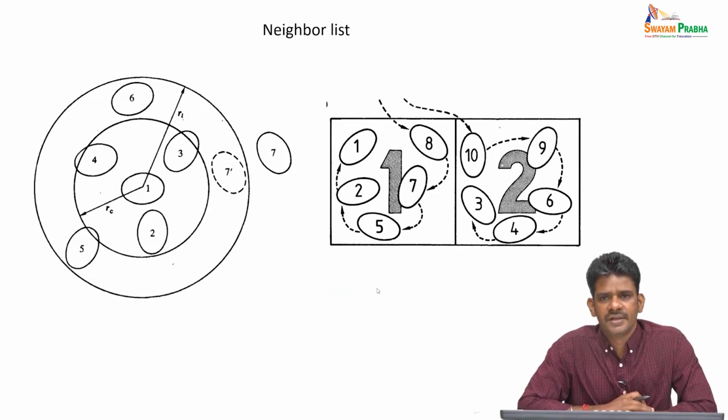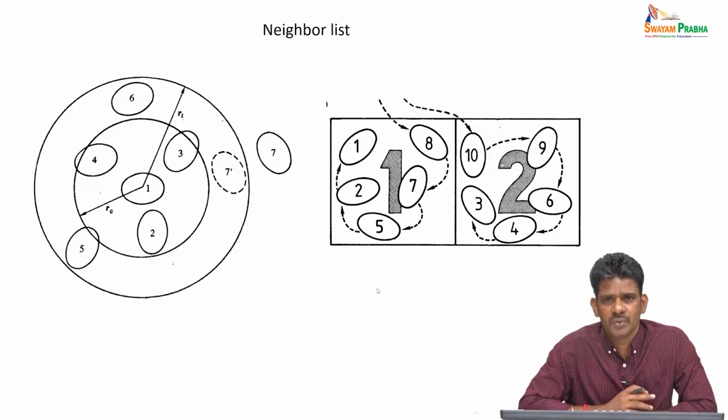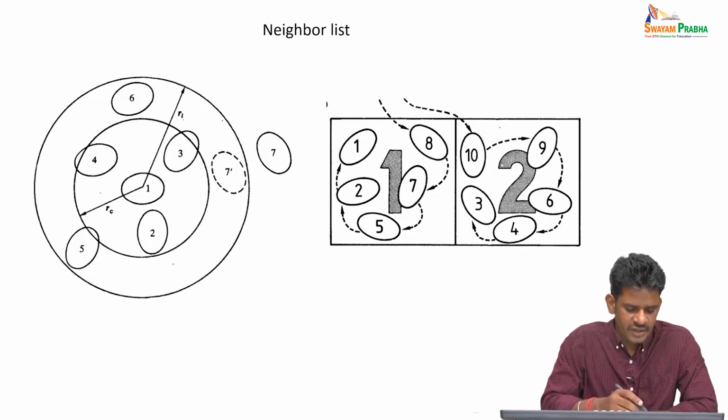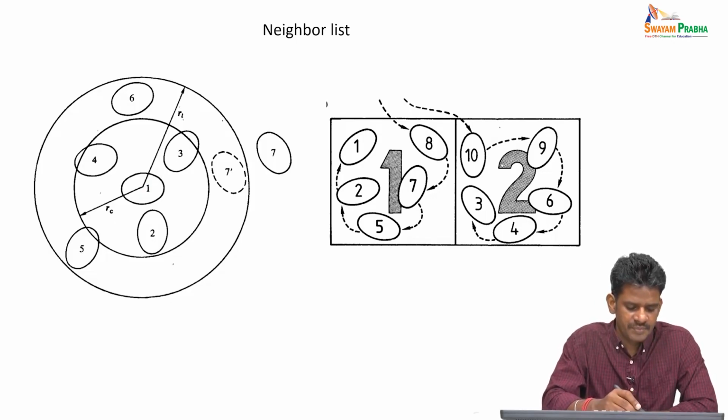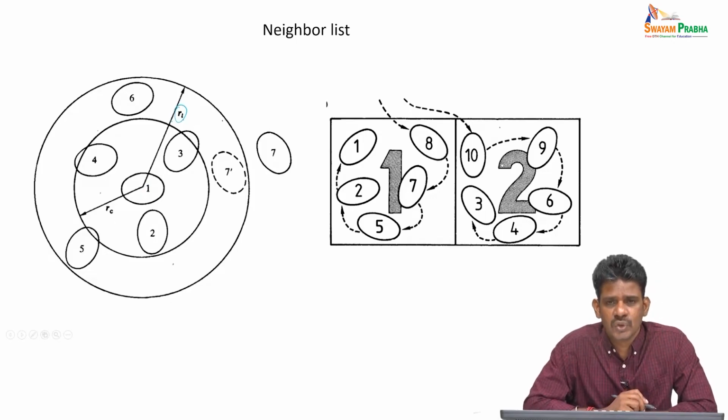Another practically important method is to use neighbor lists so that we can speed up the force or energy calculation in the simulations. We looked at two possibilities. One is the Verlet list, where about every particle we define a skin length, and then we store the neighbor information and update this list of neighbors from time to time.